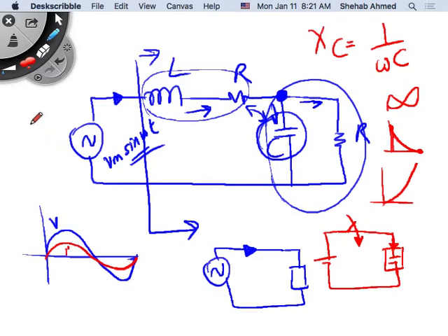Yes. So if you look at, for example, IC equals, okay, what's the capacitor current equals what? C dVc by dt, right? So the current through a capacitor is equal to the differentiation of voltage across the capacitor, right? So what is the differentiation of a sine wave? A cosine, right? So assuming the impedance is a complete capacitance, if it's a cosine, then it's going to look like something like this, right?